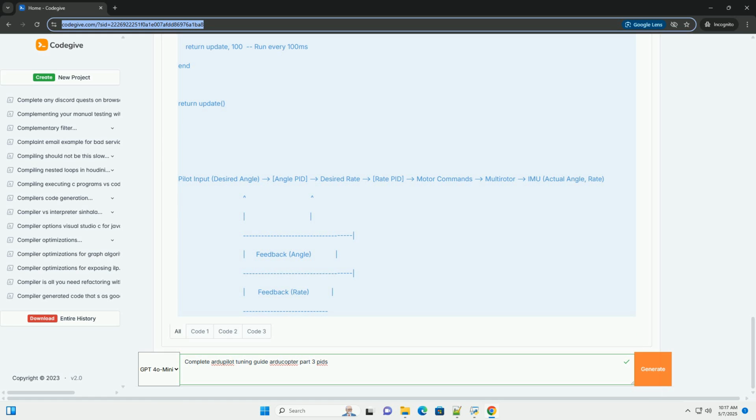Oscillations. Wallowing. Motor saturation. Drifting. 7. Advanced tuning considerations: filter settings, notch filters, dynamic harmonic notch filter, using logs for fine-tuning. 8. Code examples, Lua scripting for tuning: a basic script for modifying PIDs, an advanced script for log analysis and visualization. 9. Conclusion.